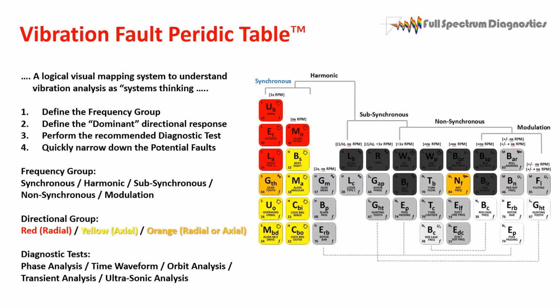So you're going to have to take data in more than one direction, usually a horizontal and axial if you can get them, and vertical is kind of hard to get too. But I've done a couple of things where I'll get up on a ladder and shoot down on the top of the machine so that you can see it, or go up on a mezzanine and look at it from there. Anyway, there's a lot of things you can do.